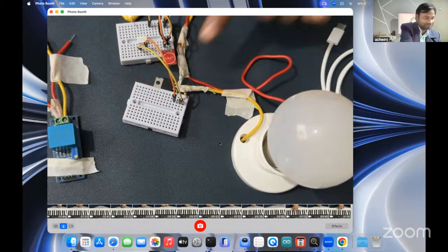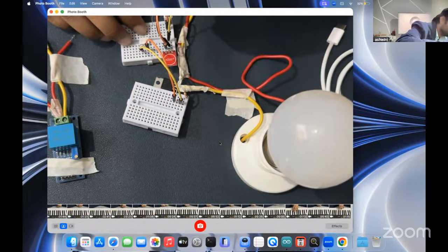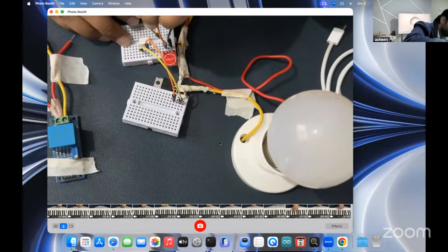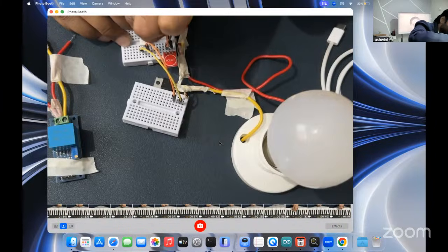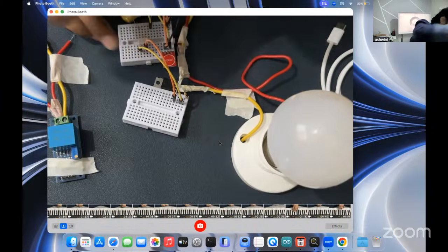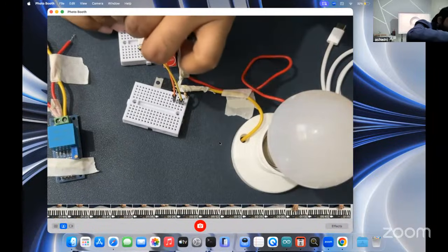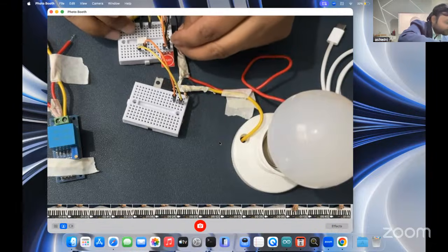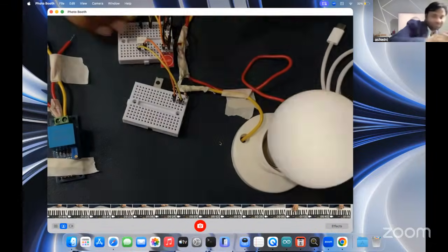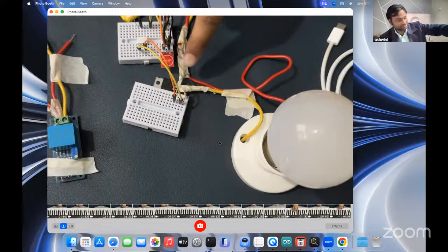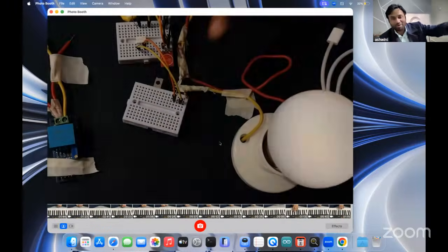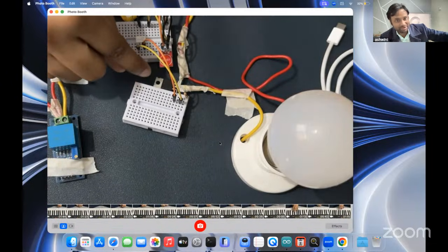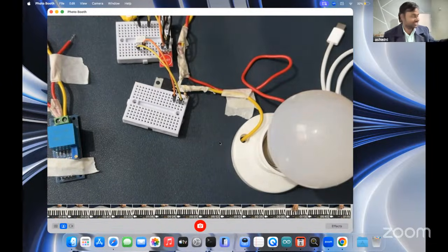One minute. This is the optocoupler output. Yeah, we need to make the ground common between the optocoupler and the touch sensor. The ground is not here, so let's make the ground common with this one. Now whenever I touch this, it will turn on. See, I touch it. So I'm controlling the whole AC power using this single IC, the BT136 TRIAC.